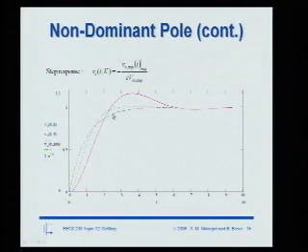And so this is our settling time. Looks a lot like the settling time of a single pole system. So this curve, which is probably really hard to see, is the single pole system. And if let's say you have a factor of 100, that means that equivalent pole is just not in the picture, right? And the settling time is, again, almost exactly the same. And then if you go to the case of 1, that's 45-degree phase margin that we just looked at, you can see that it does overshoot by quite a bit, almost 20%, and then it settles down.